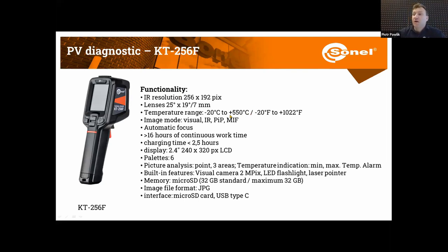Important things are to have the visual and infrared image, because sometimes when we look with our eyes at the measured object and at the screen of the camera, it may be hard to recognize what we are actually looking at. Because the infrared image and the hotspots it shows may differ from what we visually see.